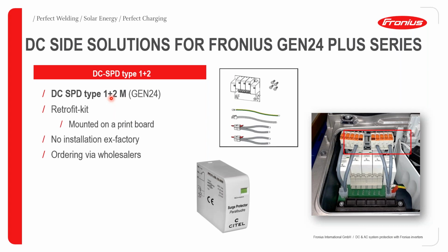As another example, for the Fronius Gen 24 Plus inverter, we also have the possibility for DC SPD type 1+2. This is only available as a retrofit kit. It's not possible to order the inverter with the DC SPD ex-factory. The SPDs, as we can see here on this photo, are mounted on a print board, which you are then going to retrofit into the Gen 24 Plus inverter. So there is a provision made for retrofitting the print board with the SPDs.